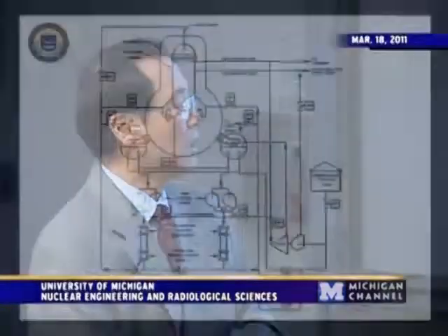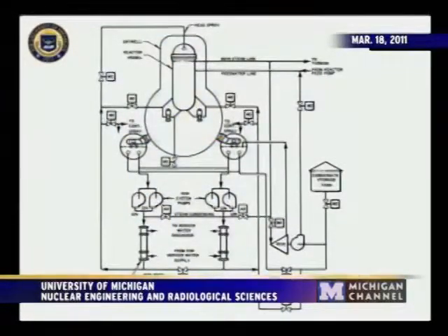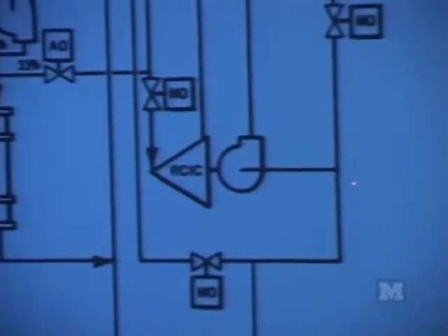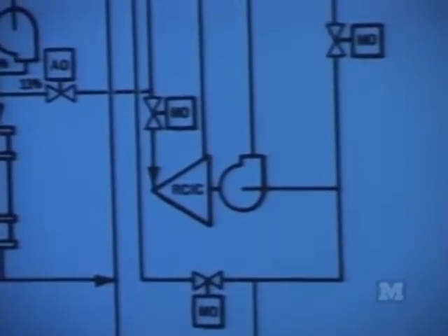And as a backup system, the emergency diesel generator came on. And it provided cooling for about an hour or so. But another wave of tsunami hit. And apparently, the fuel supply systems were either knocked off or blown away. And diesel generators stopped working. That's when this steam-driven backup pump came on, the RCIC pump came on. And again, it was able to use steam that is still produced from the reactor core and pump condensate storage tank water into the reactor vessel.